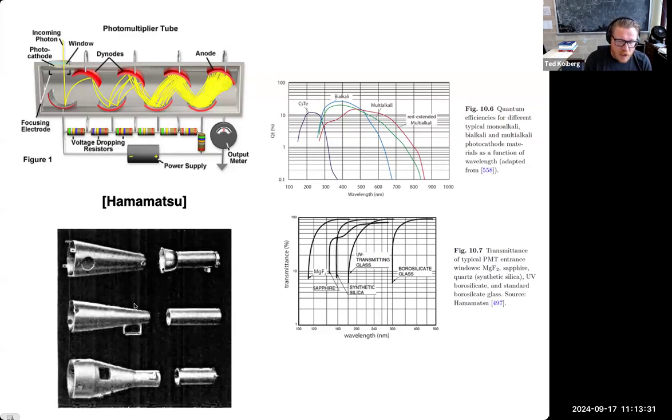So you use sheaths made of what's called mu metal. This is a special alloy, which is typically mostly nickel with some amount of iron, molybdenum, and some other impurities added to it. And basically, this is a metal which has a very high permeability to magnetic fields. That is to say that magnetic field lines will prefer to pass through this metal as opposed to the photomultiplier tube that it's shielding. So you place this thing inside of one of these mu metal shields, and that will largely protect it from external magnetic fields. These are kind of going out of fashion in physics now. Other photodetectors, silicon-based photodetectors, which have basically one amplification stage, which is microscopic instead of these large macroscopic arrangements, have a lot of advantages. I won't talk about that now, but we will revisit it later.